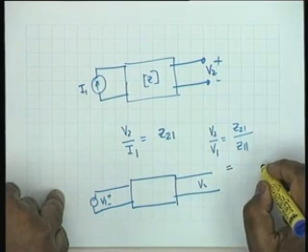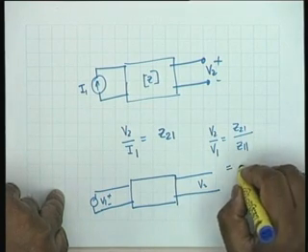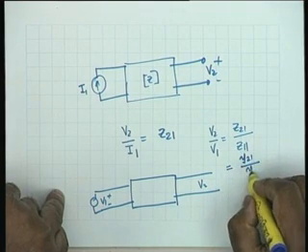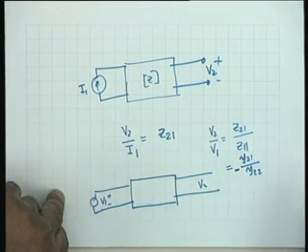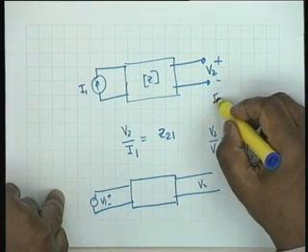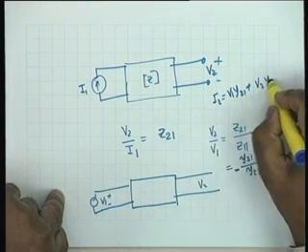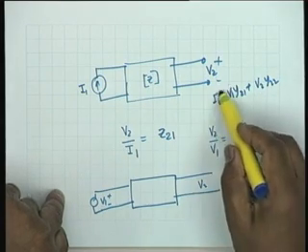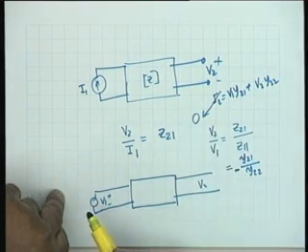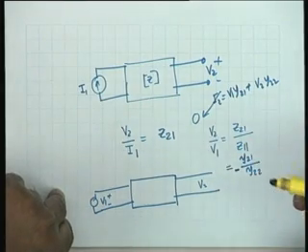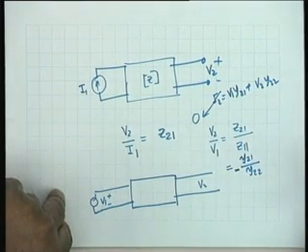And if you don't recall, this is Y21 by Y22 with a negative sign, and it comes because I2 equals V1 Y21 plus V2 Y22, and I2 is 0. That's how it comes. These derivations, how you get this, you should be able to remember. Simple things like this. Now we complicate matters a little bit.